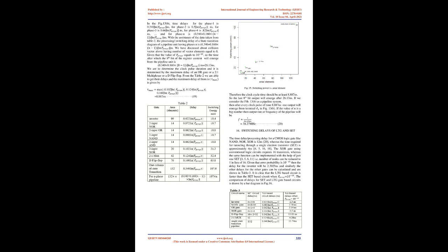Fig 14b, delay vs capacitance. We have found out the area/element numbers for every case of gates, its switching delay, and switching energy consumption for the corresponding individual linear threshold gate, using the same methodology as adopted for the Boolean gates. The switching power versus area/element diagram regarding our present LTG-based circuits is shown in Fig 15.